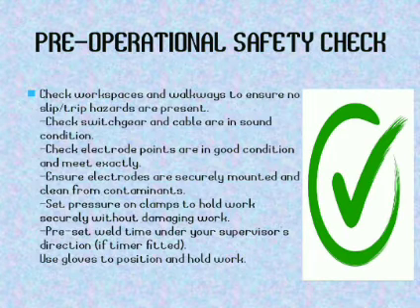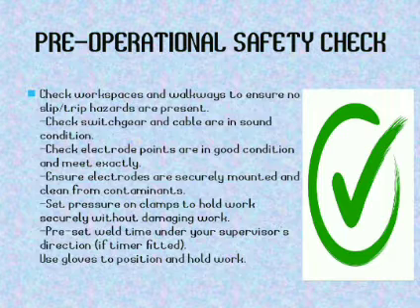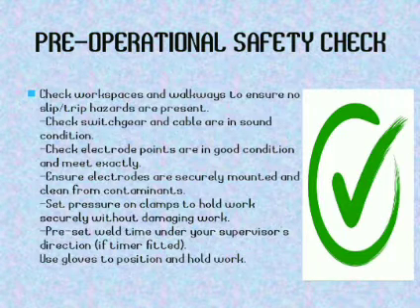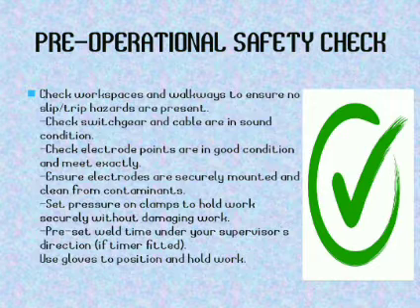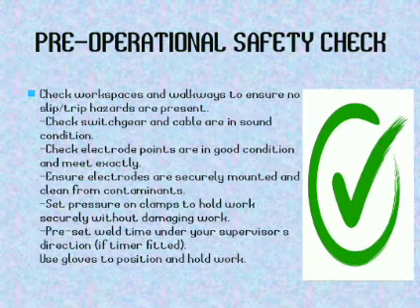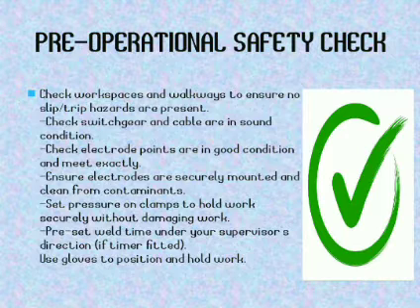We also have a pre-operational safety check. Check workspaces and walkways to ensure no slip or trip hazards are present. Check that gear and cables are in sound condition. Check electrode points are in good condition and meet exactly.